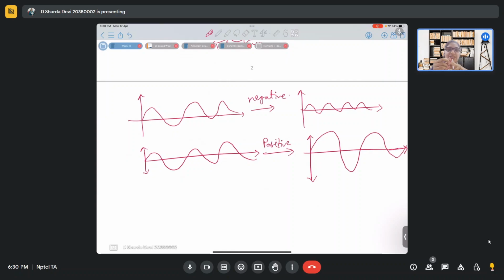This positive feedback input will again be amplified, twice, so square times. Then it will be fed back again. It will continuously feed that input until it comes to a resonant state, and that's where we get a stable sine wave, if we are talking about a sinusoidal oscillator.